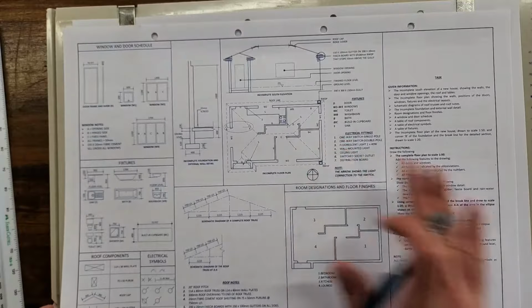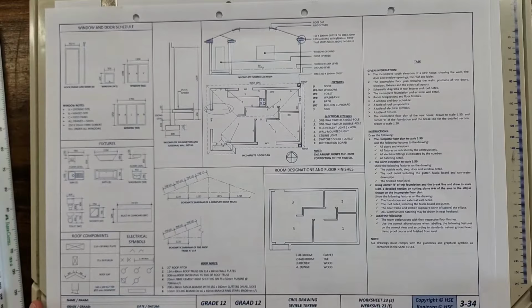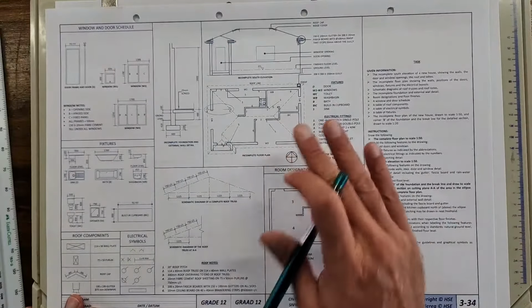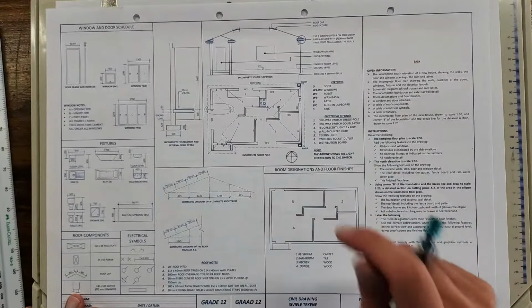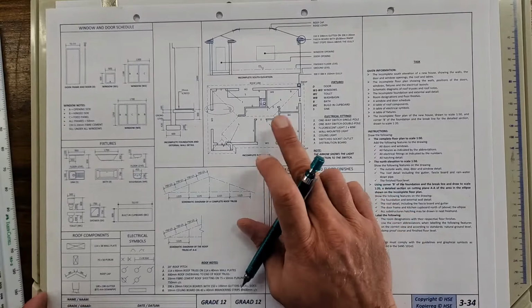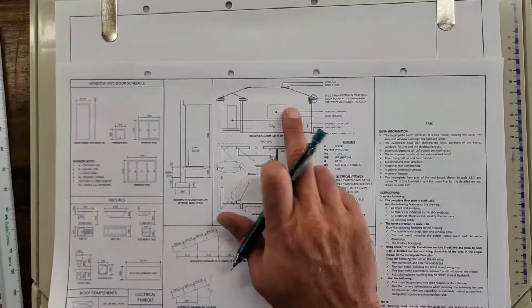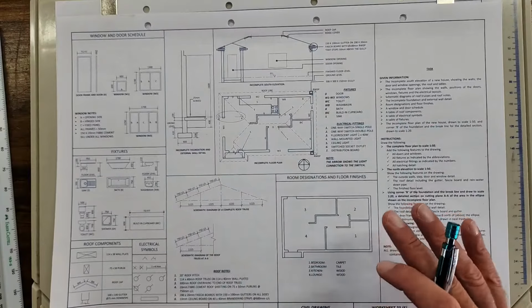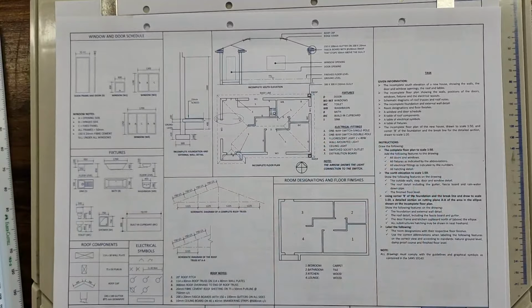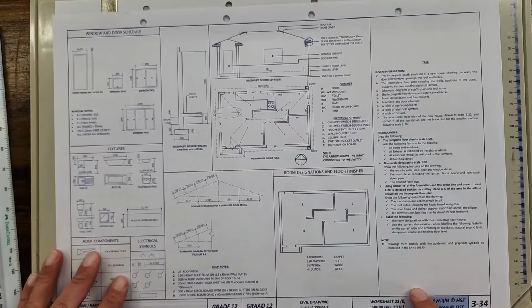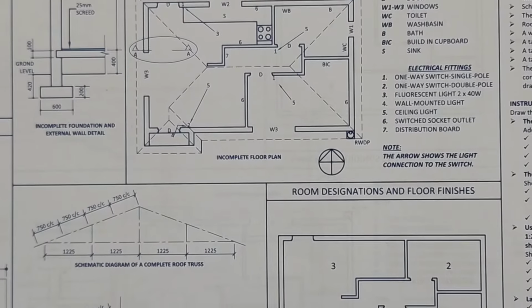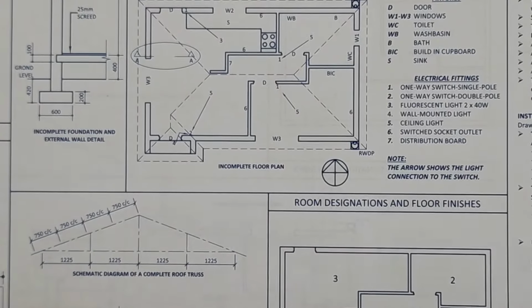It is our last civil drawing that we're going to do together before we get into two-point perspective, so I'd like us to make sure you are up to speed with this. For this lesson I'm going to focus not on the floor plan, but more on the elevation and the sectional elevation that is required as part of this drawing. First of all, when you get a question like this, you're going to familiarize yourself with what is given and make sure you understand all the components. Remember, you can be sure that every part of this drawing, what is given here, is going to be for your information.